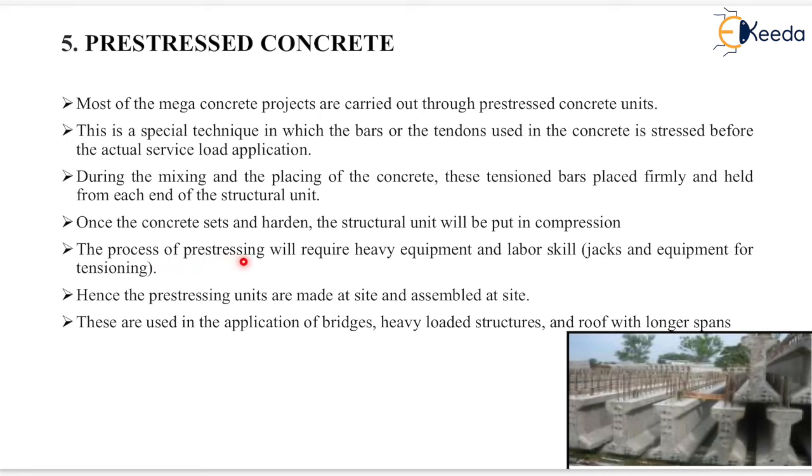The process of pre-stressing will require heavy equipment and labor skill, that is jacks and equipment for tensioning. Hence the pre-stressing units are made and assembled at site. These are used in the application of bridges, heavily loaded structures and roofs with longer span, that is shown here.